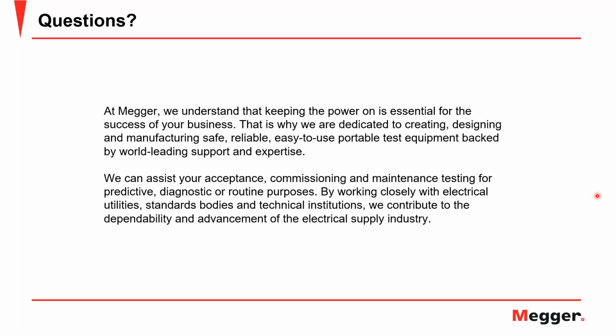As an anecdote, a couple of days ago, I was talking to a CT manufacturer who was complaining about a customer asking them for a CT, and the only thing that the customer knew was the load that they were going to run in that place. They didn't know the short circuit level. They didn't know what they were going to connect to the secondary of the CT, or how far the CT was going. So my point is, the more information you get from your system, the better your system design is going to be.